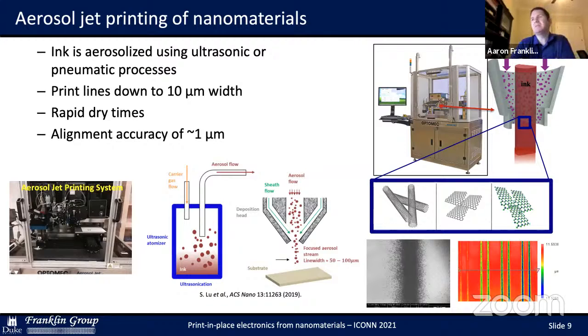Yeah, I appreciate you asking that. Is it possible? The short answer would be yes, because the range of viscosities that you can adapt a print process for in an aerosol jet is really broad. Even if you're dealing with relatively large particles in the ink, you can adapt the features of your printer to accommodate those features and that viscosity.